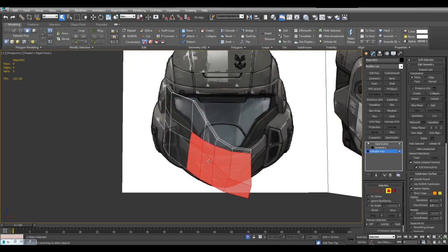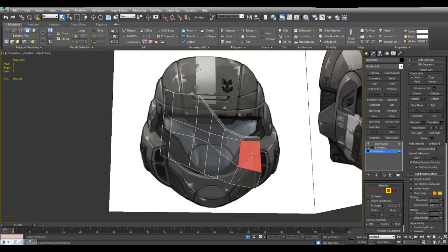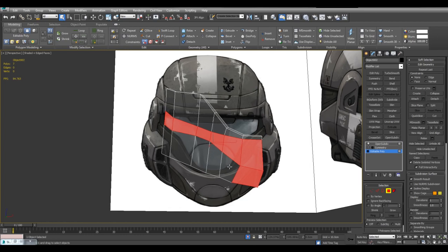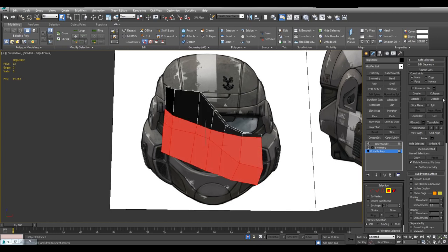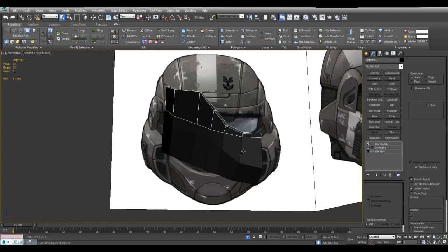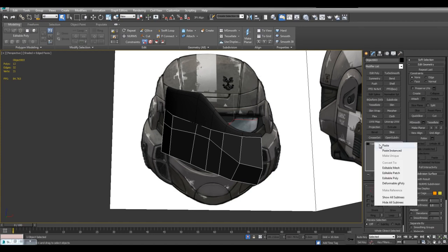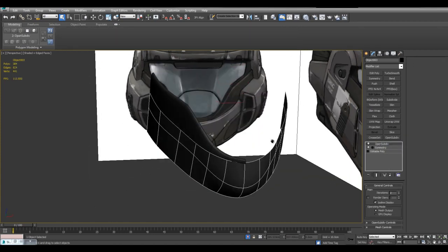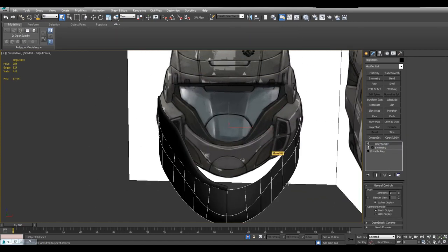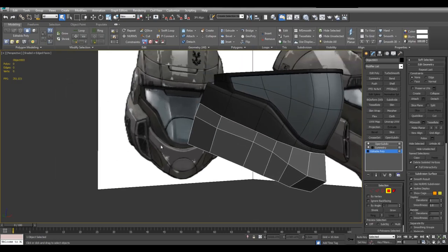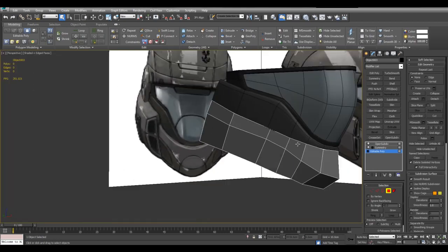So what I need to do is select all these polygons, or I can simply click here, hold Shift, hold Control and Shift, and there we go. And I can simply detach that. And I can paste those modifiers right here and give this a lighter material. Now this geometry is a separate object. I need to give it a little bit of thickness.